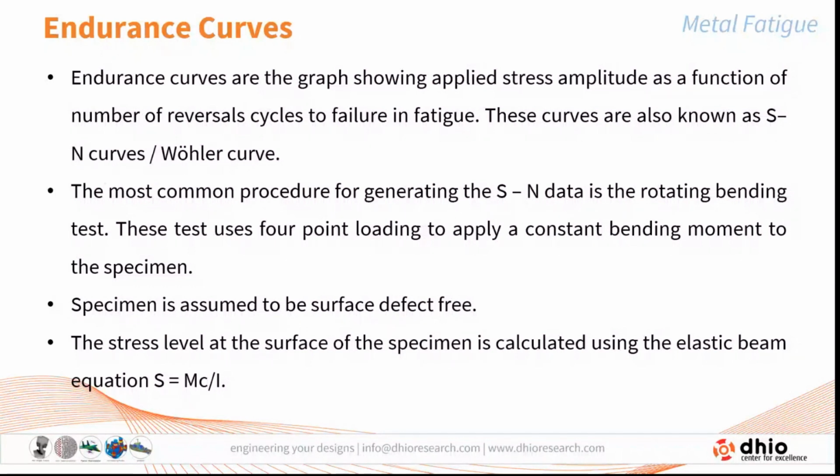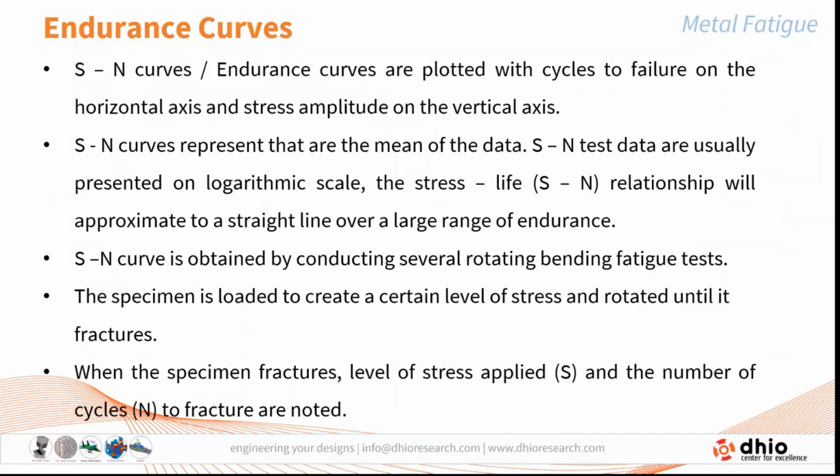And the stress induced in the member is calculated based on the elastic beam theory given by the beam equation, where the stress induced is equal to the moment M times the distance c of the outermost fiber from the neutral axis, divided by the area moment of inertia I.